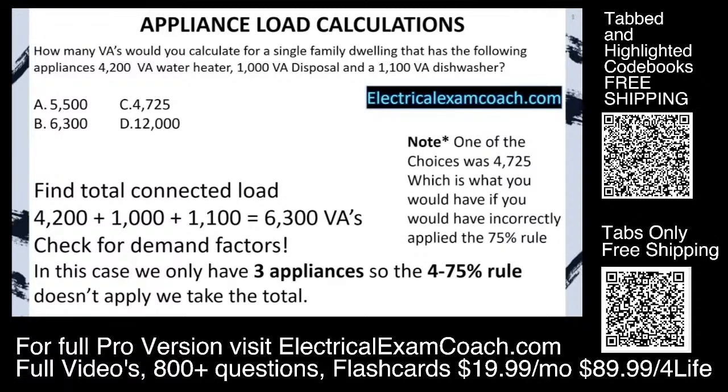I do want to note that one of the 4 choices was as if you had incorrectly applied the 75% rule. In this case, because we only have 3, we don't apply any demand factor at all, and we take the total connected load at 6,300.